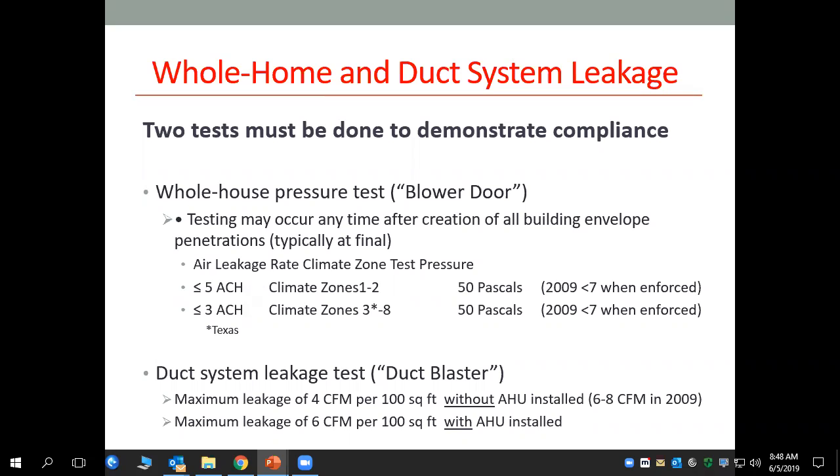But I think the important part of this shows where we were and where we are now in our air exchange requirements, how much tighter houses are. I get a lot of questions about ventilation and what you've designed, what you make, that's good for foam houses. Well, absolutely, but also if you've got a house that's 3 ACH 50, that is an extremely tight house. It needs effective ventilation. It doesn't ventilate on its own very well or not at all.